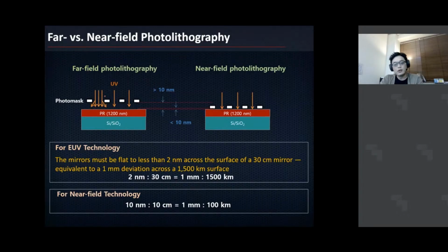I think most of you are familiar with what photolithography is. Even though we say typical photolithography is contact printing between the mask and a photoresist-coated surface, it's not true, because think about the size of the wafer. Let's say you start with a very small wafer, a 4-inch wafer, and then you need a 4-inch mask as well. Your mask contacts the surface, and you expose it under UV. And the 4-inch wafer has a diameter of about 10 centimeters, right?